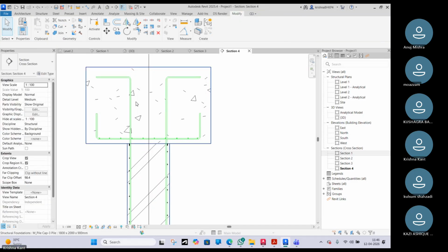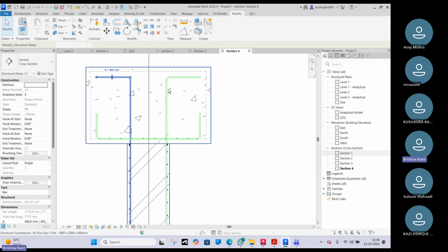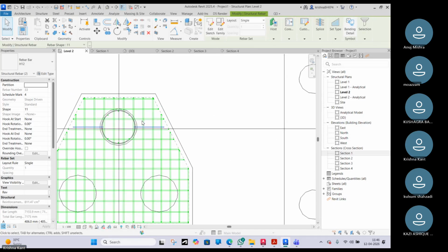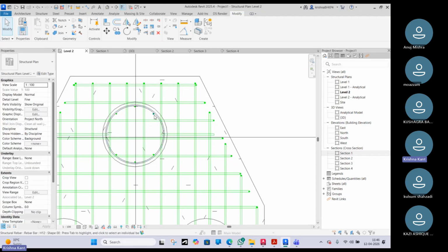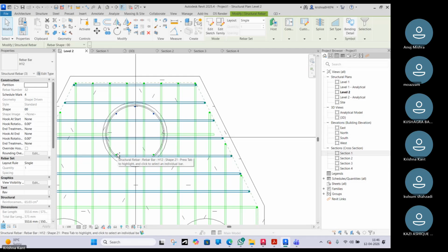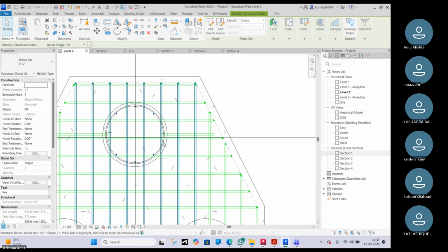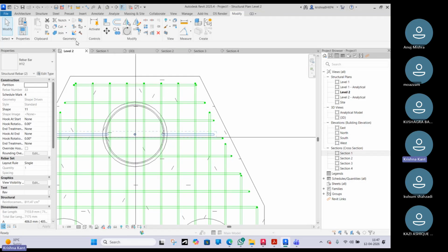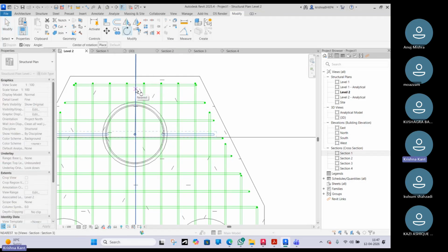Okay. And then select these two, these two are a sketch. I will delete all this because I will provide it again. These two, and rotate it while copying. So rotate it from center, provide at 45 degrees.